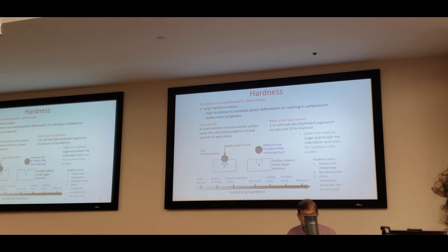So there are different methods to determine the hardness. One is the Rockwell hardness: the difference in depth of penetration resulting from the application of an initial minor load followed by a larger load. You will see some videos, so you will understand it better. You have an indenter here. Initially, a minor load is applied, as in the case of the Rockwell hardness.